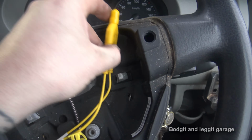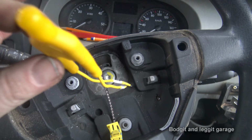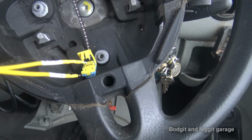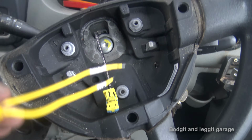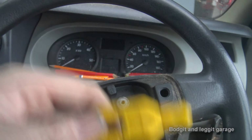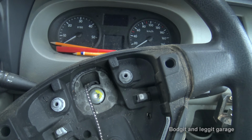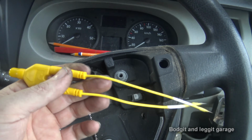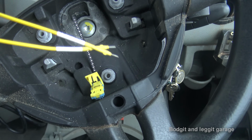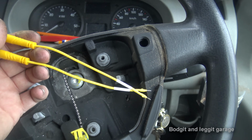We have now put our resistor in here. So this essentially becomes our airbag. So I should be able to connect this into here and turn the engine back on. If our light goes out or stays out, we then know we have a problem with our airbag and we need to get our airbag replaced. So I'm going to do that test first, and then if it doesn't, we're going to do a few more tests and see exactly what the problem is with this.